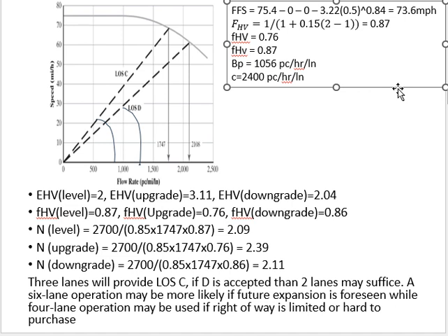Once the graph is done, now I need to make the lines which will indicate my level of service. I need to make these diagonal lines. You see the dotted diagonal lines, right? I need to plot them to show where is my level of service. In the question, they are asking for level of service C, and they are saying D is also at C.